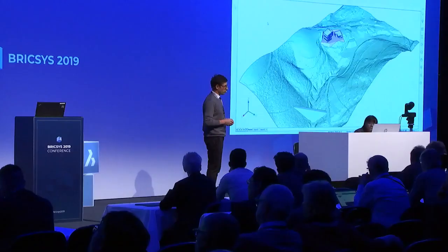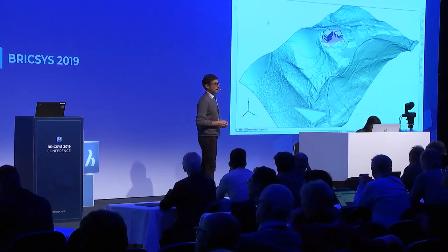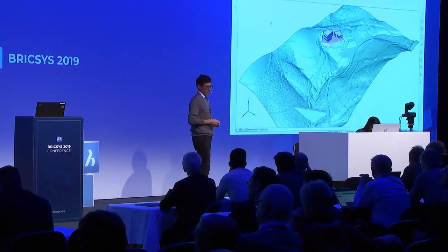And by those alignments, you can precisely define the center line or geometry of the road or other linear object. The traditional way of designing the alignment goes like this: you design the horizontal alignment in plan view and you design the vertical alignment in the profile view.